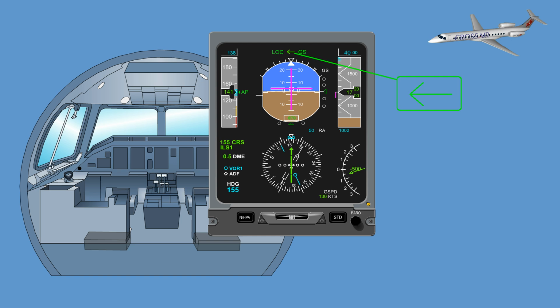A flight director couple arrow in the center of the mode enunciator area indicates to which flight director the autopilot is coupled. If the Cat 2 condition is stabilized, a green Cat 2 legend will be seen. In case a signal becomes invalid afterwards, the green Cat 2 legend changes to an amber Cat 2 legend.